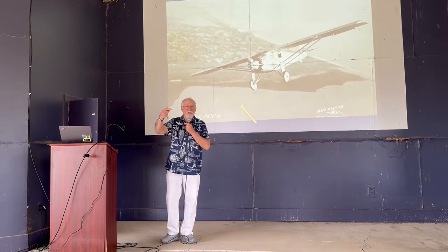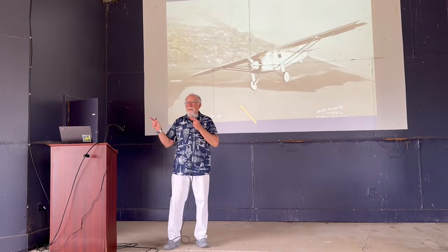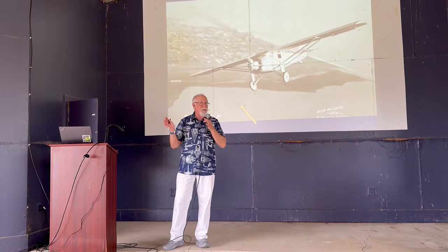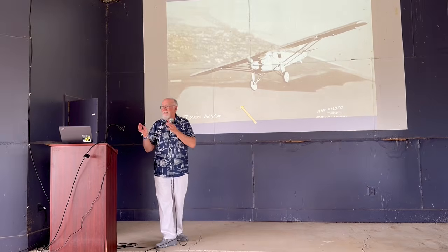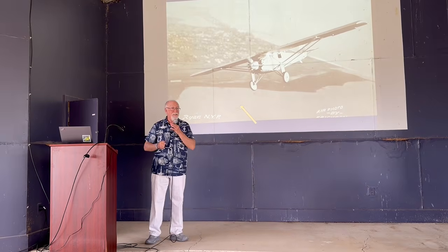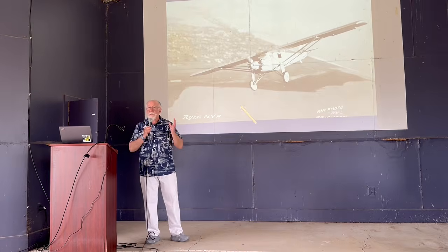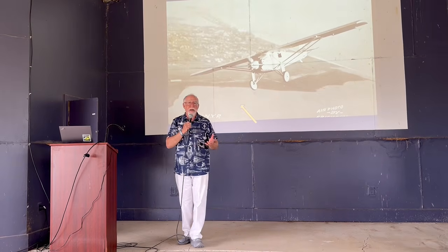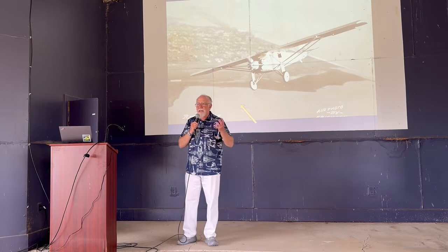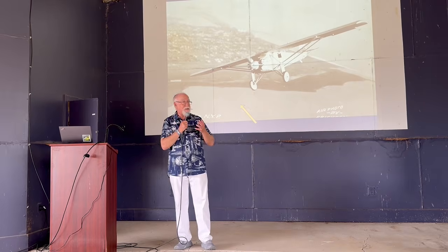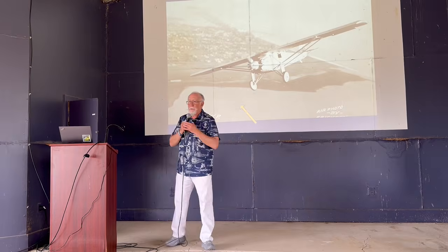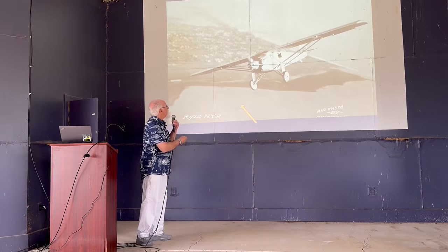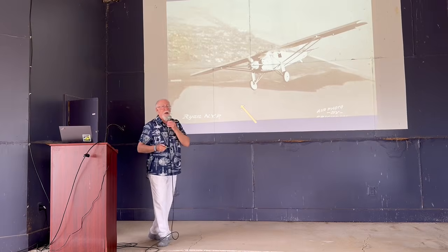And you take a look at the design compromises they made along the way, because they also had to build it in some insanely short period of time. I think it was 90 days, to try to beat the other competitors. So he's talking to Donald Hall. One of the things is, okay, you've got to carry this insane amount of fuel. To make it balanced, you want that fuel near the CG. Well, where's the right place to put the fuel? In front of the cockpit.